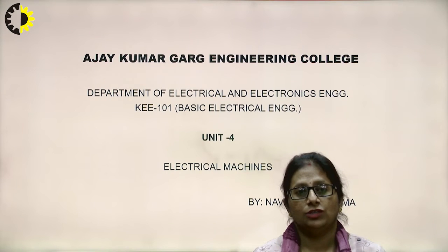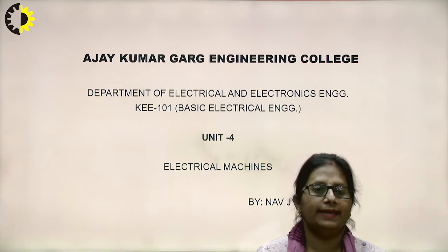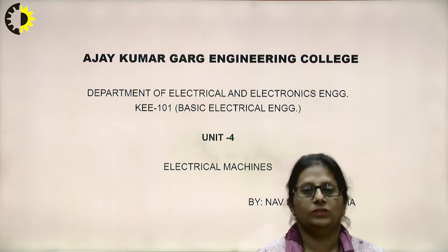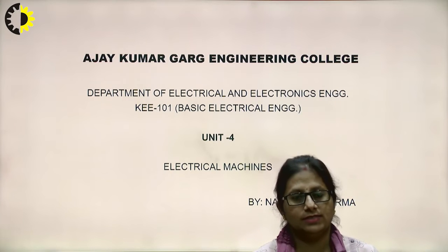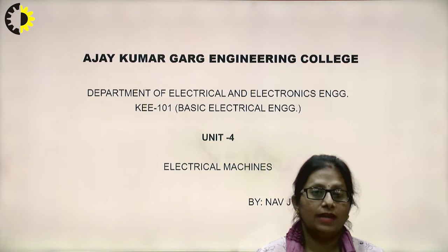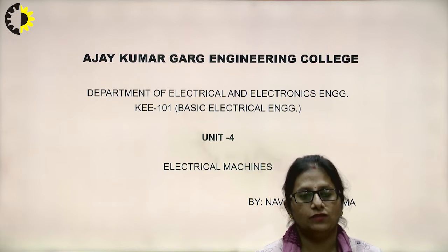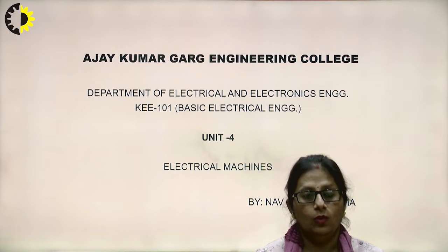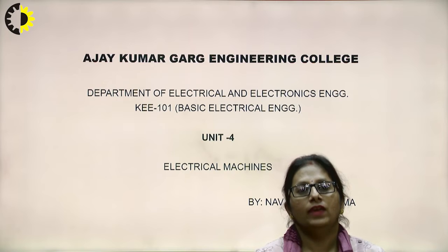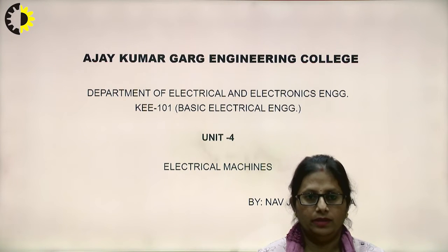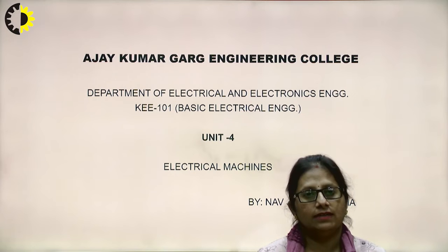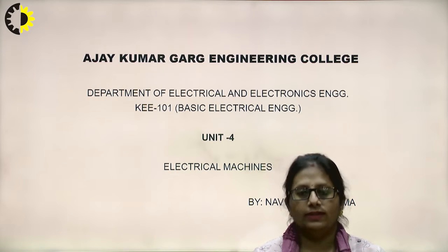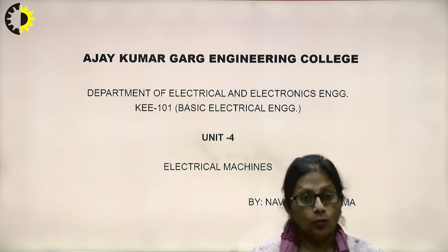Once again, in the rotor construction, we find 2 types of constructions. It can be either the salient pole type or the projecting pole type, which is generally considered for low speed applications, whereas for higher speed applications, such as turbines of higher speeds, like turbo alternators, there it is a cylindrical rotor. There the poles are not projecting, but the unslotted portion of the core forms the pole part.